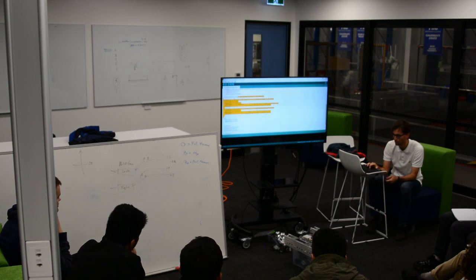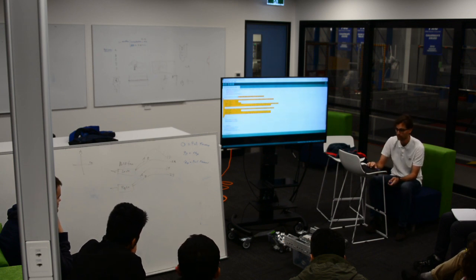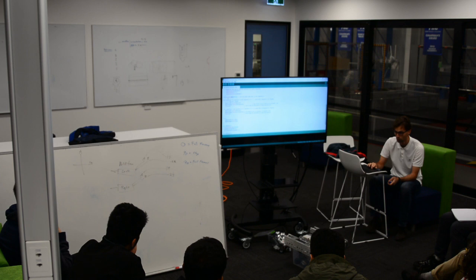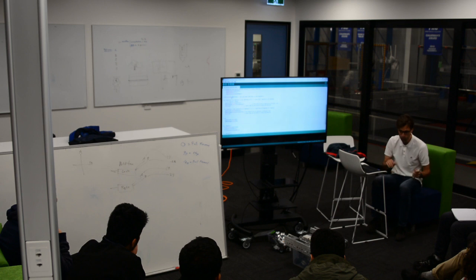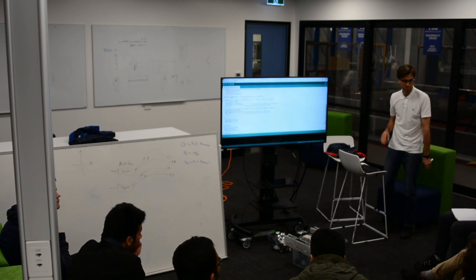So if 6 is low, the robot shouldn't really go, although there are some issues with these delays that it's unable to check the state. It only checks the state of this thing after completing a full forward and back cycle, right? It's not checking the state of this very often. It only checks it, because look at all these delays. It runs this for loop for 180 times 15 milliseconds. Then it runs this for loop for 180 times 15 milliseconds. Then it goes back and checks the state. So there's some problems with that.